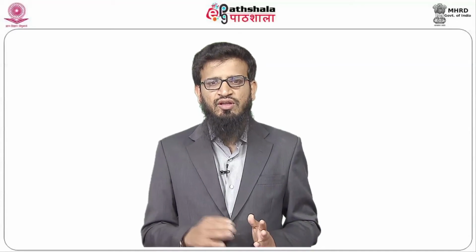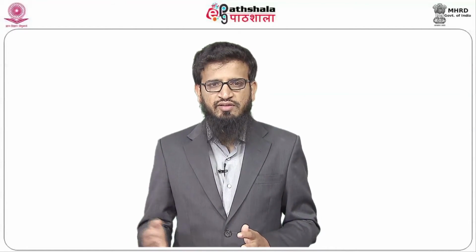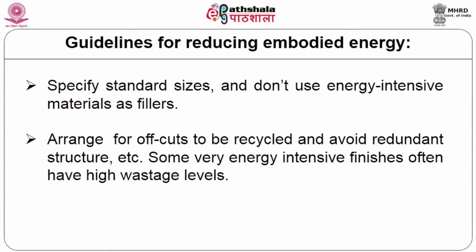Avoid wasteful material use. What it means here is design buildings in such a way that if the plywood is 8 by 4, what you get in the market, design the interiors in such a way that you use that 8 by 4 rather than wasting the material, because at the end of the day that waste is added on to your embodied energy that has been thrown out. Specify standard sizes, that is what I mentioned before, that you specify proper standard size, do not use energy intensive materials as fillers and everything. Arrange for offcuts to be recycled, avoid redundant structures, etc.